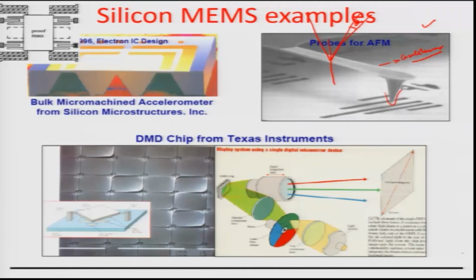So, obviously, the mirror would deflect by theta by 2, and based on such bending, one can really map the progression of the tip in the z direction, and such a z direction can be topologically mapped as a reconstructed image which would give you an idea of how the surface looks like. So, depending on the resolution of the scanning on a surface, one can get a very good perspective of almost atomistic scale features on the surface by an instrument like this.